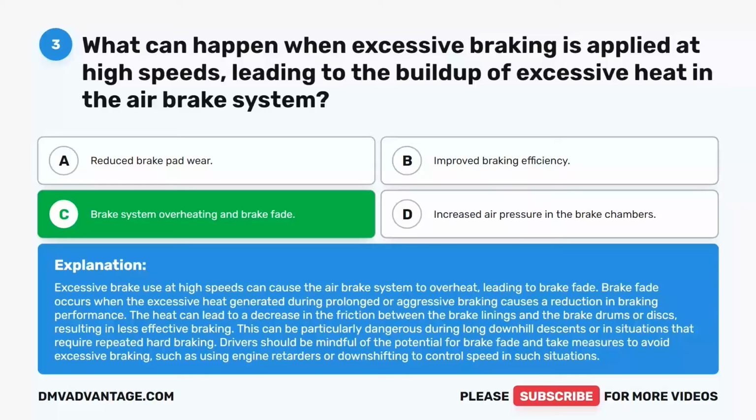This can be particularly dangerous during long downhill descents or in situations that require repeated hard braking. Drivers should be mindful of the potential for brake fade and take measures to avoid excessive braking, such as using engine retarders or downshifting to control speed in such situations.